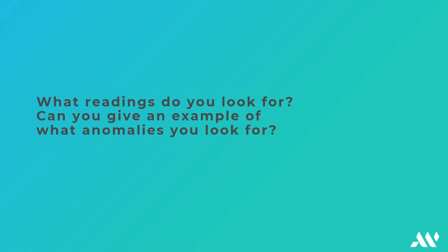Is it a pretty sizable family, or just a couple hanging out around the fundamental? Or even a crest factor that's trending up off the time waveform, which is the gauge that we use for determining the severity of the problem. Is that crest factor data? I covered it when I did the case study earlier.